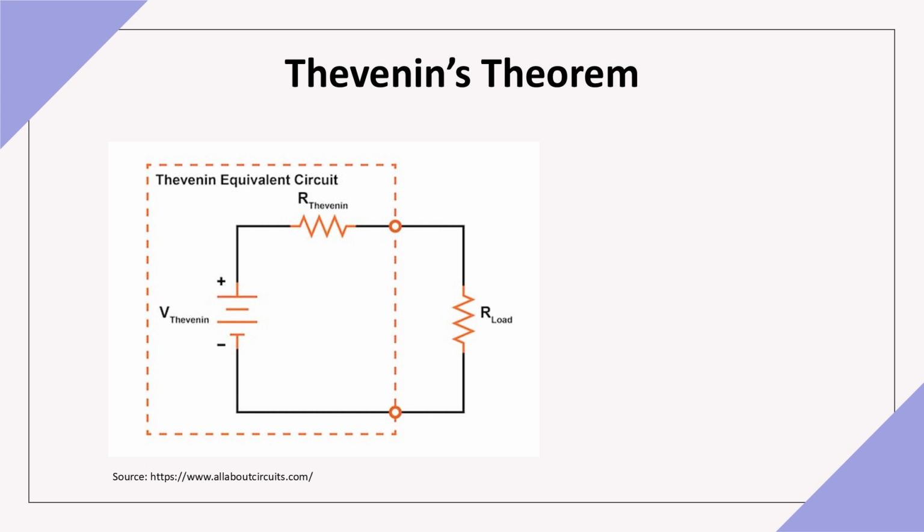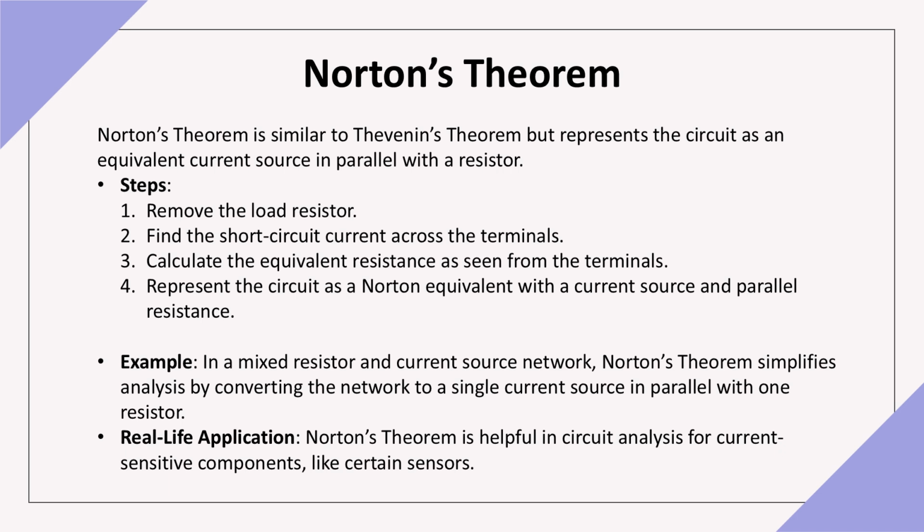This simplification is particularly valuable when you need to design maximum power transfer circuits, analyze loading effects, troubleshoot complex networks, and design power supplies. Norton's theorem is the current-focused twin of Thevenin's theorem. Here's a practical example. Consider a current sensing circuit in a battery charging system. Norton's theorem helps us understand how the sensing circuit will respond to different battery states, from fully charged to